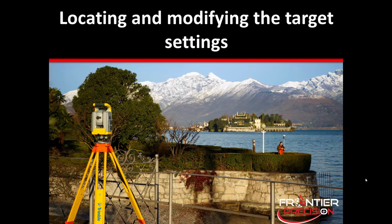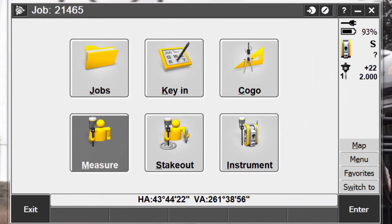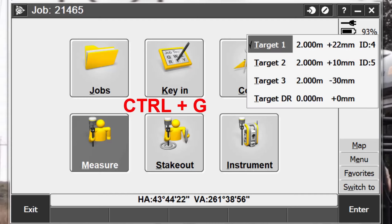First, let's take a look at locating and modifying the target settings. When you're connected to a conventional instrument in Trimble Access, the target icon, along with the instrument icon, will appear in the status bar. The number next to the target icon indicates the numbered target currently in use. To alternate between targets or to edit the target height and prism constant, you can simply tap on the target icon, or alternatively, you can pick Control and the letter G on your keyboard.